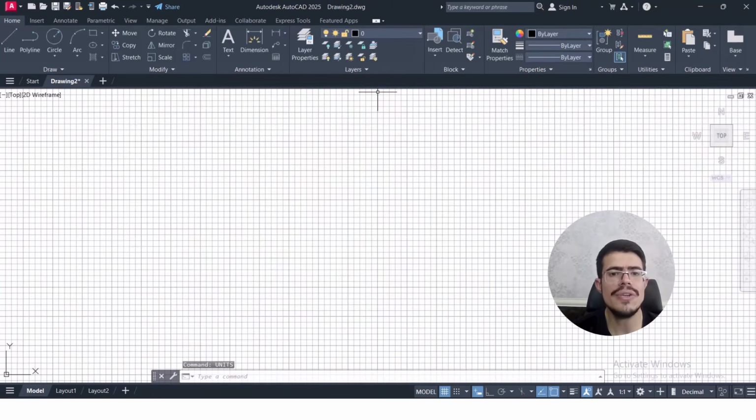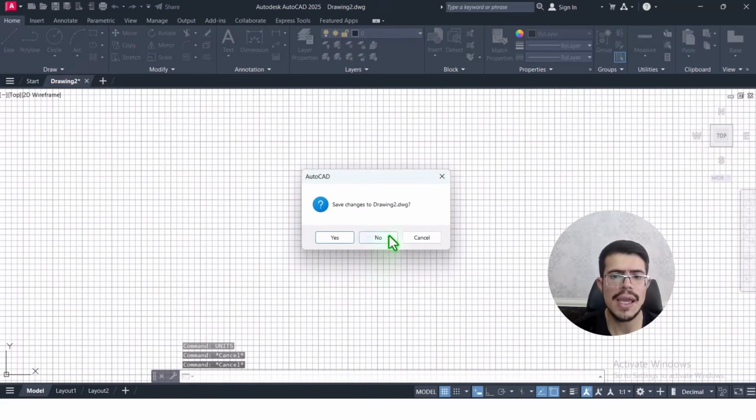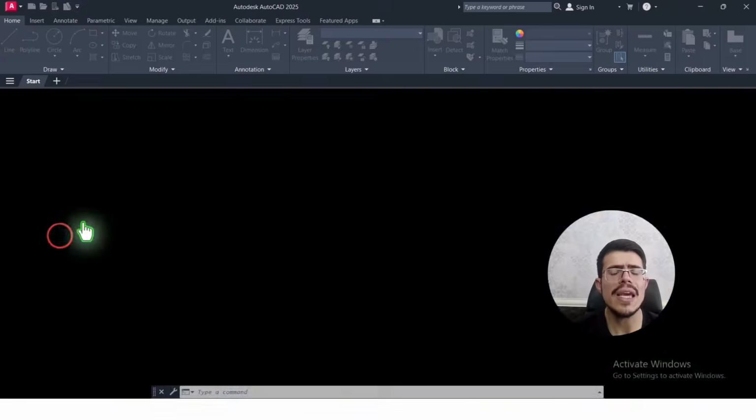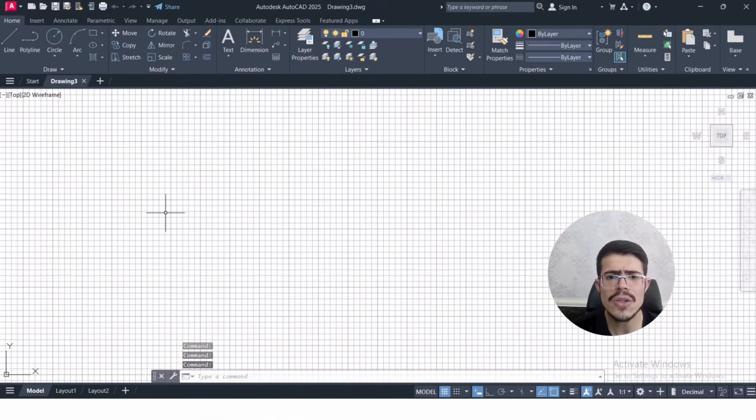So this is the difference between these two templates that I wanted to inform you about, because the units are really important during your drawings. Let's go out again and start, for example, with ACAD, maybe the ACAD ISO. But as I told you, you can browse different templates here. With ACAD ISO, what unit is this now? Yeah, you're right. It's in millimeters.